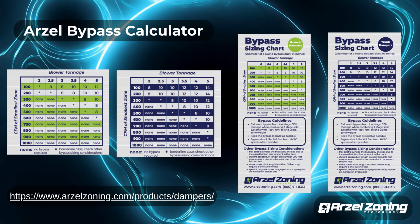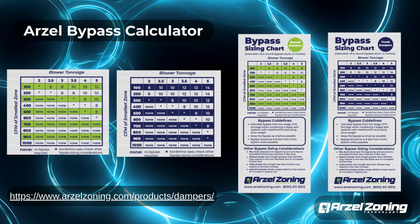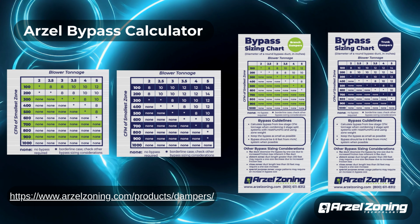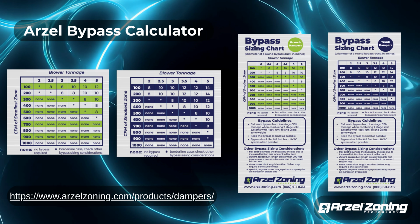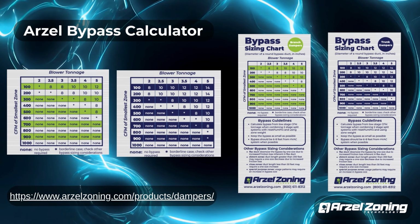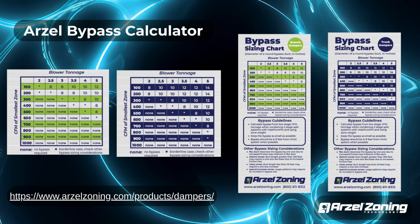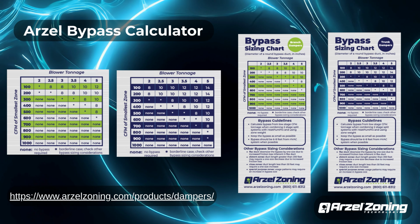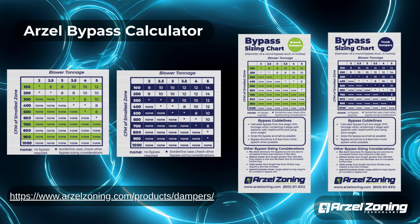If you have flex duct, it acts almost like a sound attenuator, and it reduces airflow and has higher frictional loss, and it's going to eat up potentially some of your velocity and your air noise. If you're dealing with a distant zone on the opposite end of the house from the equipment on the second floor, and I have great distances to get there, then I might not need a bypass, or I might be able to go down a size.